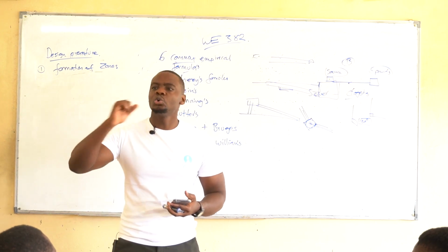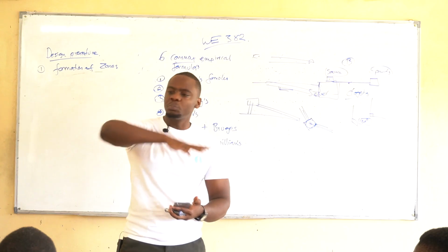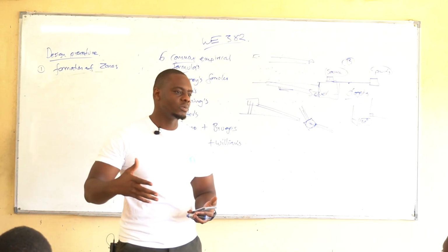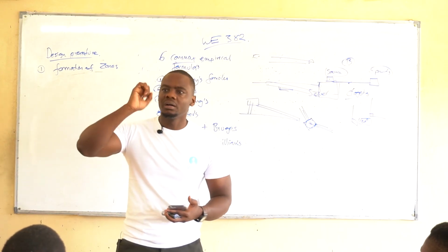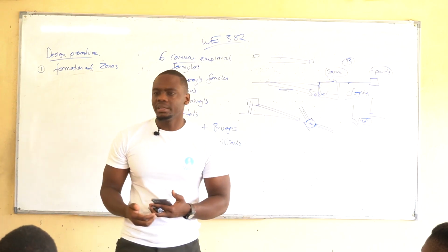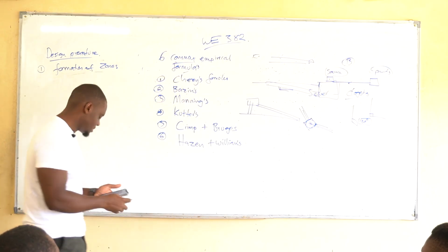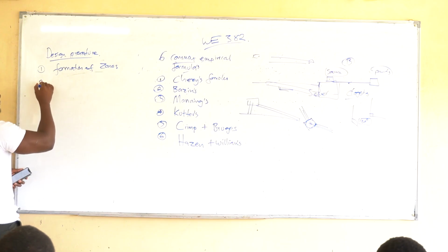So draw your contours so that you know which ones are your high points and which possible areas are low points you can take your waste to. Identify where your roads are, identify where the houses are. Do you have pipe networks, water networks that are running through, and then you decide. So those are zones. And once you do that, what you want to do is arrange your sewers, all right?